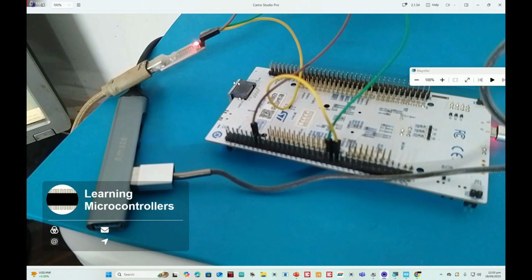You can use any serial monitor. I will use an online serial monitor called Fast Serial Terminal. You can use any serial monitor available. This one. Click on connect. Okay, the baud rate is correct, 115200. Remember, that is what we set. Click on connect.